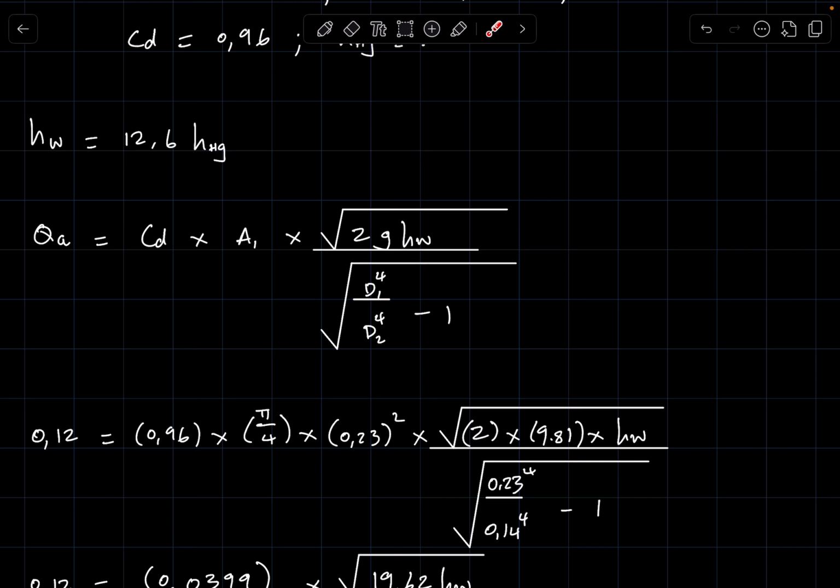If you've been given Q and you have to calculate V, you can use the continuity equation and then apply Bernoulli's, and from Bernoulli's you can get the pressure head difference, which will be P1 minus P2 divided by rho g.